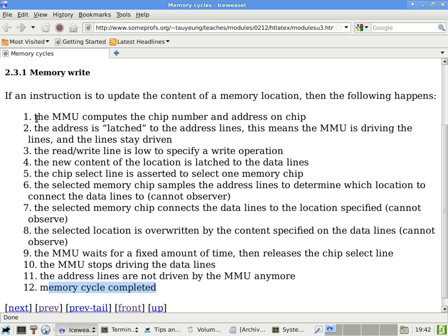You're doing the right thing because you will need all that data sooner or later. But if you have an algorithm that has random access all over the place, then it doesn't help anymore, because the stuff that you read ahead in burst mode turns out to be useless. So if you have algorithms that will do a lot of sequential reads, then DDR2 and DDR3 in burst mode will help.